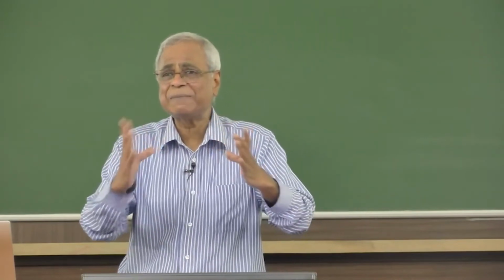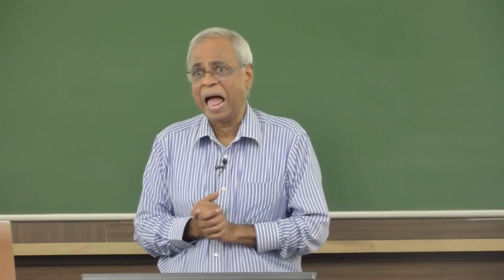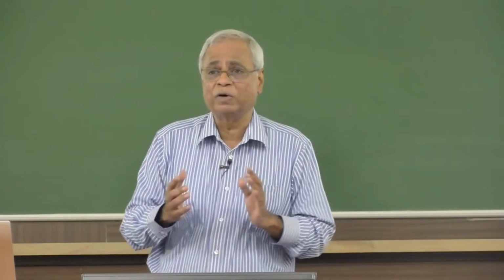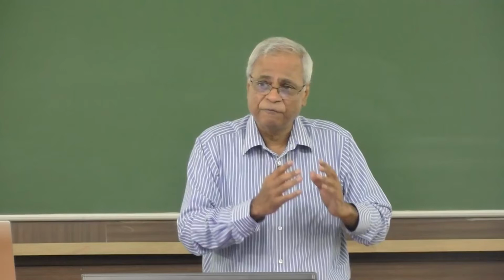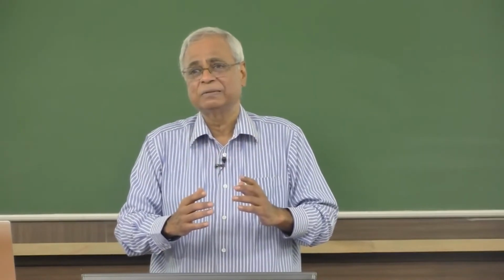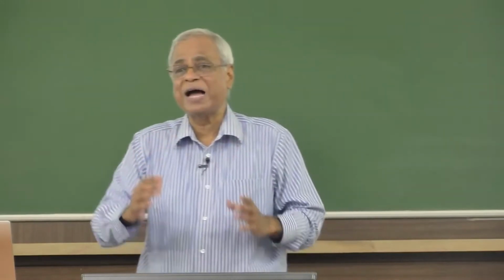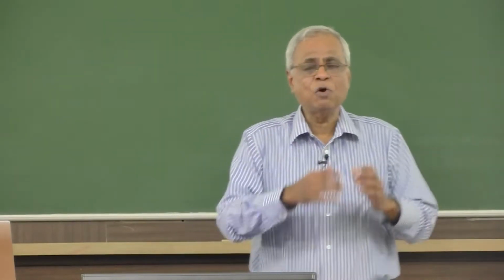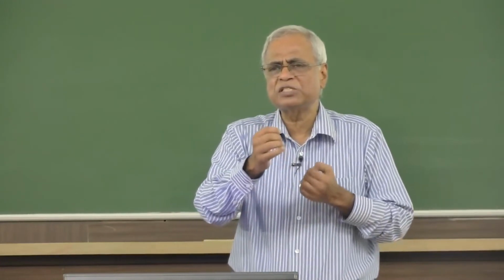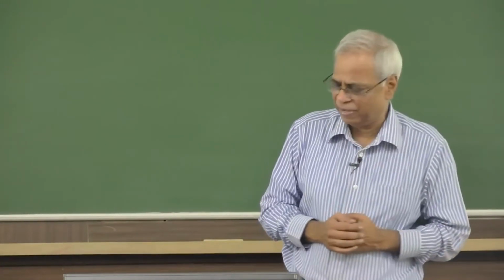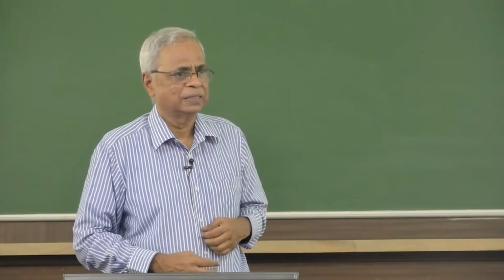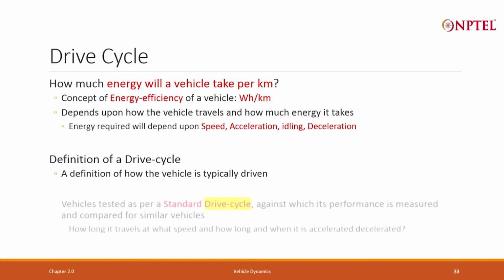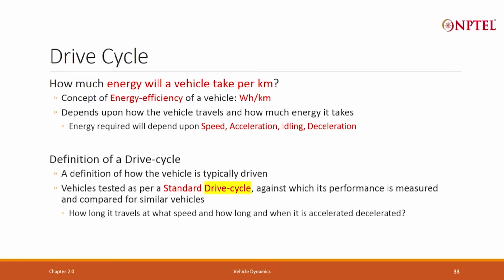So, the concept of a similar drive came in. We said that the world over, there are various entities, regulators, which define some standard drives, and you have to obtain the performance of the vehicle as per that drive, and that is the drive cycle. Based on that drive cycle we can compute the maximum power required, the maximum torque required, the energy required, and the energy efficiency in watt hour per kilometer.